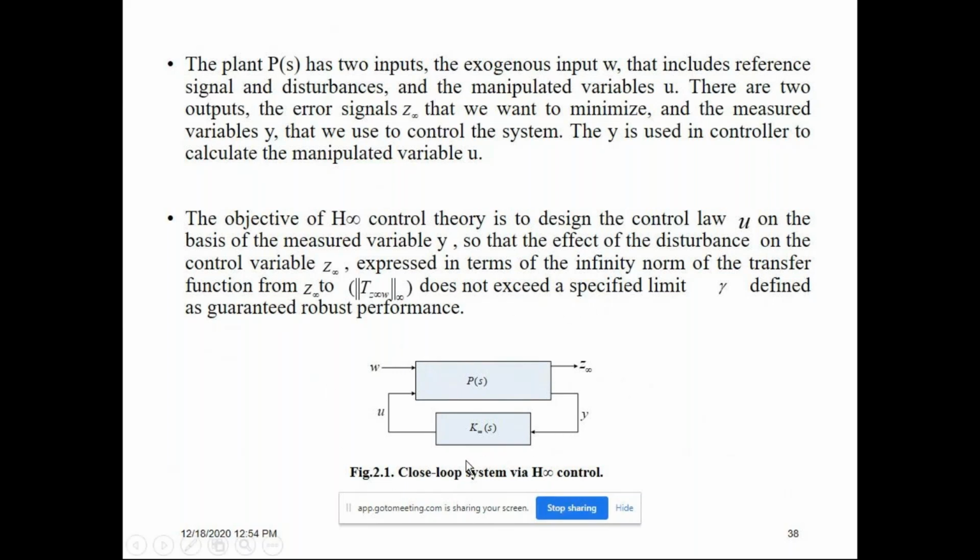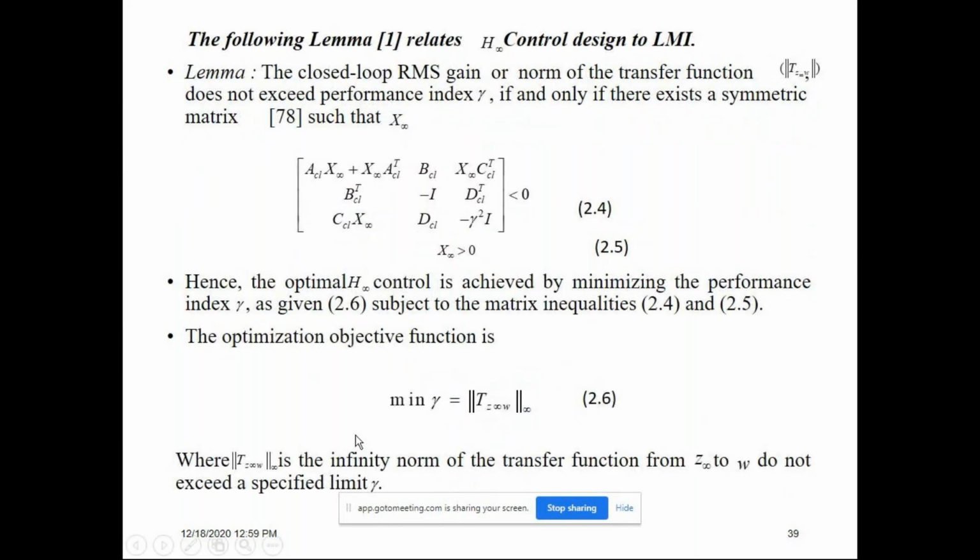You are taking a state feedback control, normally u equal to minus Kx. So the exogenous input has to be also taken in concatenation with respect to the plant infrastructure being taken into consideration. So the objective function is the minimization of gamma. You see A_CL is the augmented A, that means the plant dynamics and controller dynamics concatenated with each other.